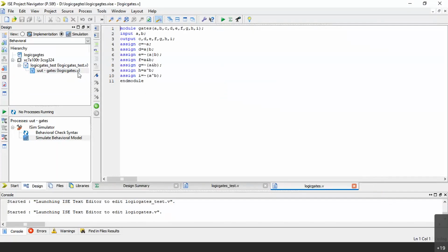Later on, you can right click on the chip. Remember, above is the project, below there is a chip, and then below there will be this code during simulation. Because I have already simulated, you are seeing the test bench on top. I told you in the last class, test bench is always called the top module because it is at the top and this is at the bottom.